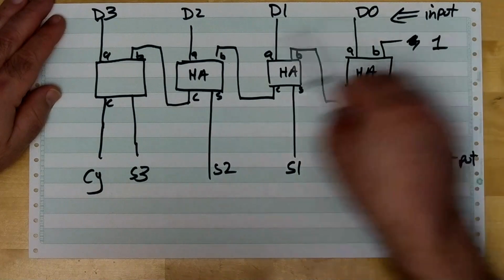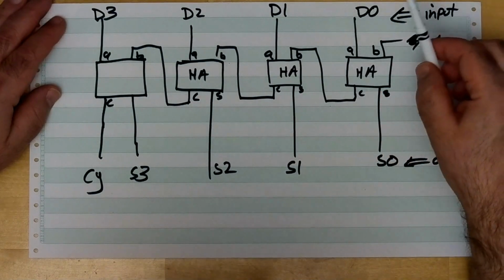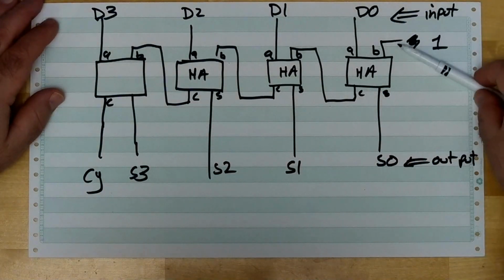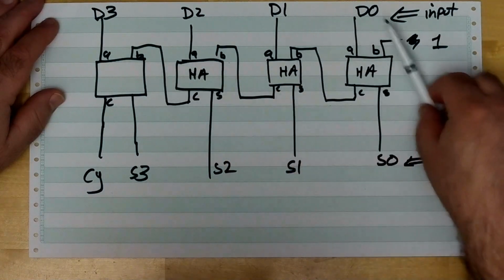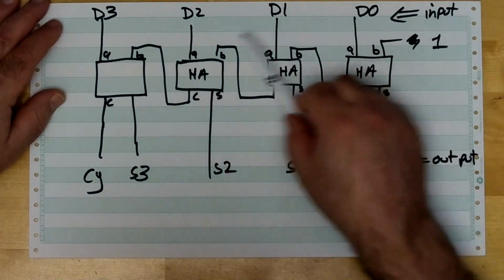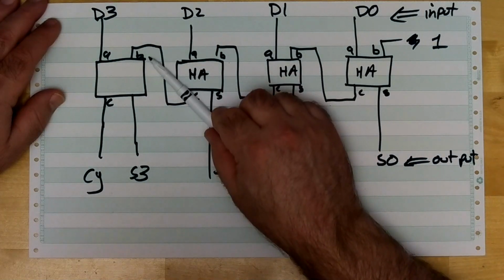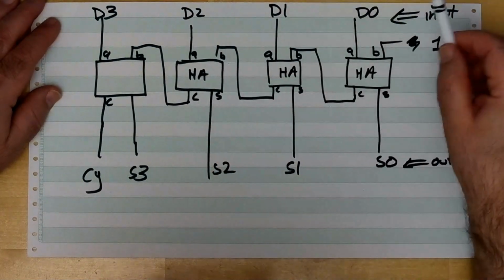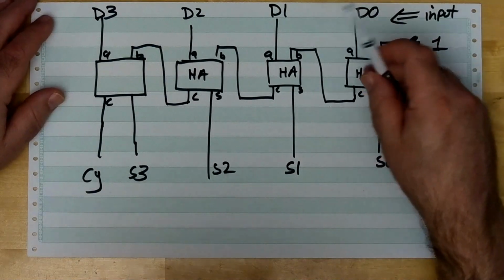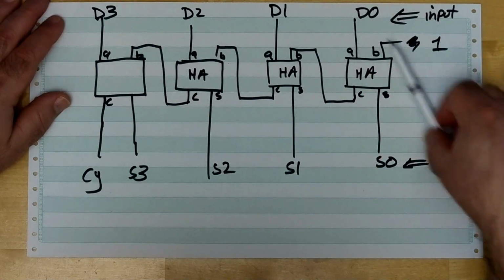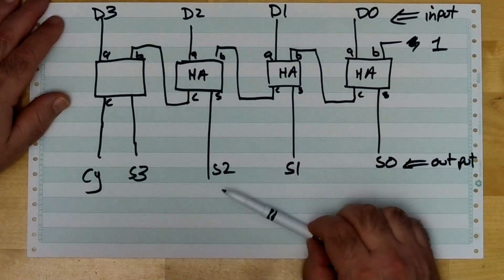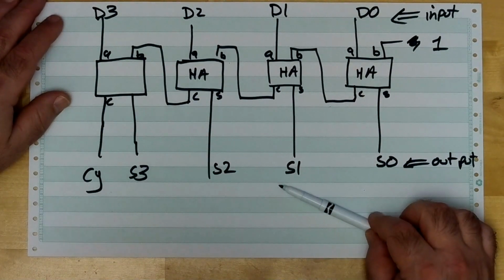So if we look at this in binary, we'll see whenever you're adding 1 to a binary number, it'll create a ripple effect on all the carries for all the least significant bits that are 1s until it gets to a 0. Okay? I'll leave that as a test to the viewer to work out. If the input here is a 0, the inputs will be left completely unchanged, as I said earlier.